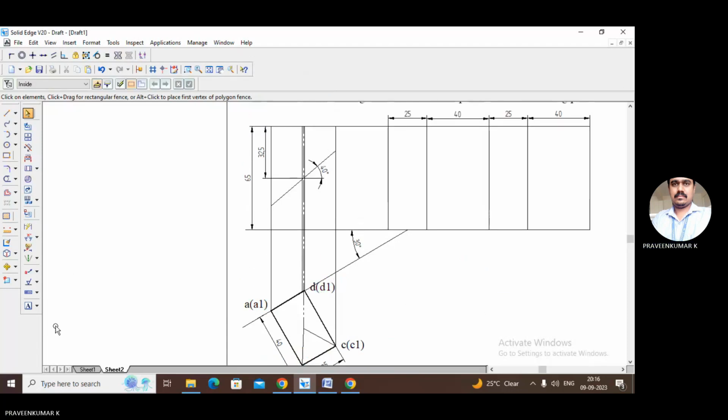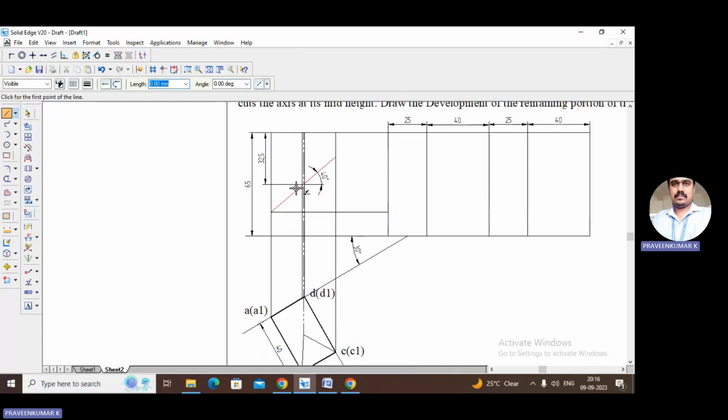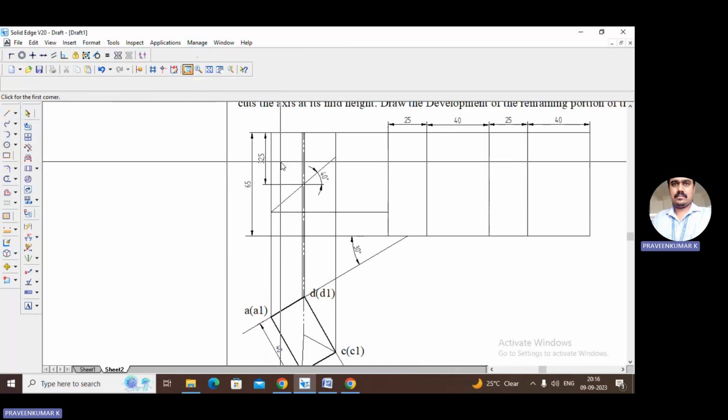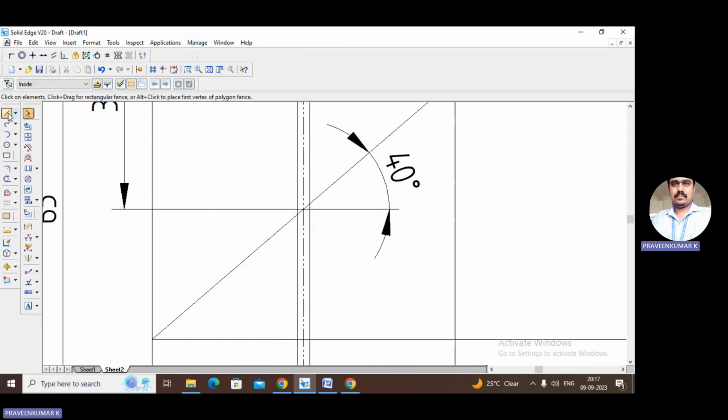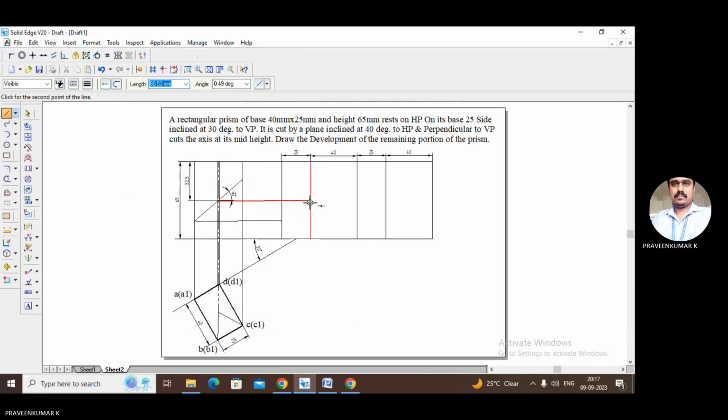And here it should be okay. And this is point 1; just mark point 2, point 3, point 4. Now extend the line. This is my point 1, from here to here. Then go to point 2, intersect B of B1. This is my point 2. If you want, you can zoom that area. Zoom that area and go to line. Select, this is my point 2, B of B1.